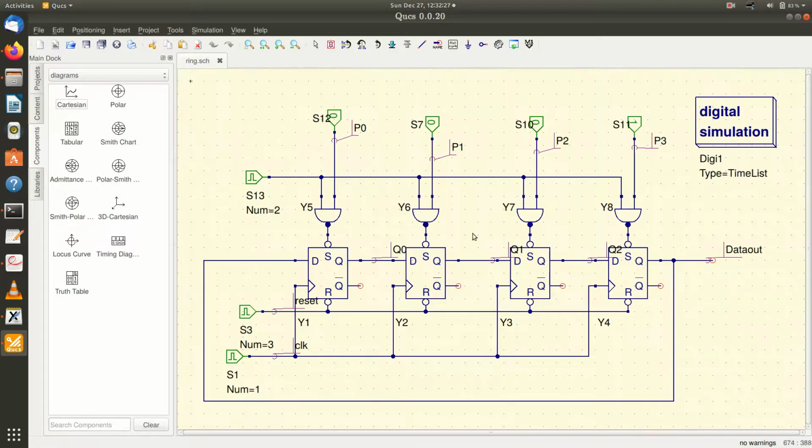You can see this operation. You can see that the Q output is fed back to the D input. Then I have to load this with some data, because the serial input is no longer there. Or you can override it, but what I do is take the data input out and connect it to the D input. Now I have loaded the data in parallel.